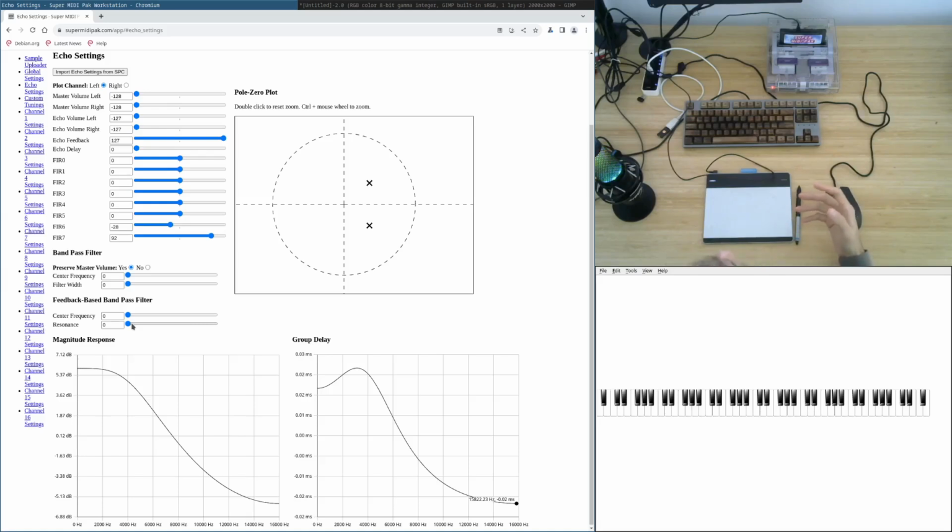I can't get into all the specifics, but because you have a mandatory 0, it's changing the magnitude response that you're looking for. You might want a certain magnitude response by placing poles in a certain place, but then if you have a 0 that's kind of popping out that you have to deal with, that 0 may warp your desired magnitude response.